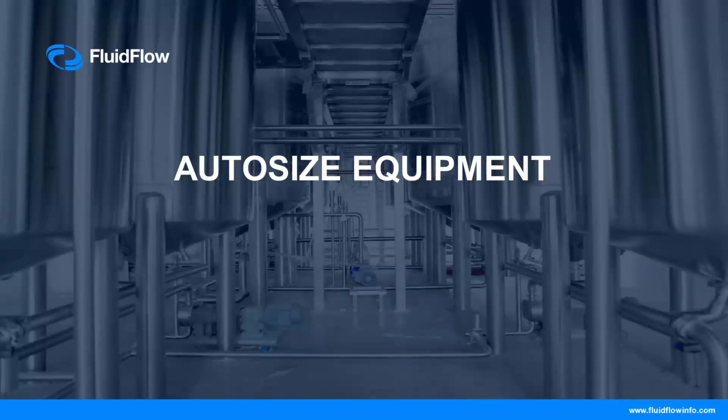FluidFlow offers a fast and effective approach to automatically size piping and key equipment in transporting fluids, such as controllers, boosters, flow elements such as orifice and venturis, as well as relief valves. The succeeding slides will guide users to the Autosize features of these components. Take note that, except for pipe components, the automatic sizing feature is normally turned off when a specific component is being rated on its performance in a system.